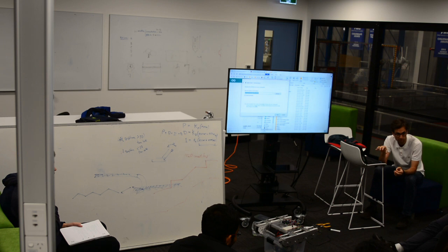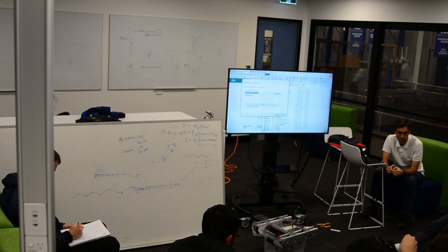That's right. Most off-the-shelf PID controllers have 3 little turn pots, one for the P, one for the I, one for the D, and you do exactly that. You run it, and you typically look at some sort of step response, or listen to it, and you adjust the P, then the D, then the I, I think is how it goes. But look up a protocol. We might have 9 things: left motor, right motor, and then the correction for the line tracker. You might have to tune the left and the right independently, but start with them being the same.